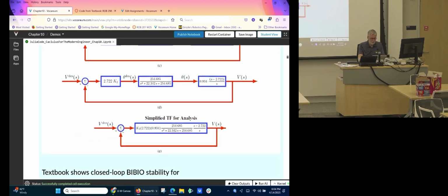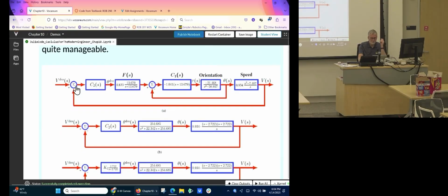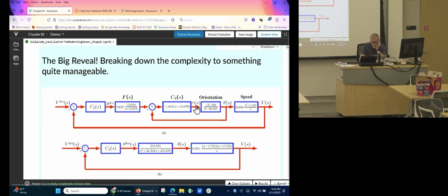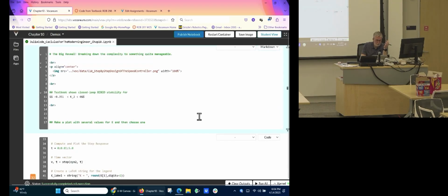Now what I want to do is the following. Here's the torque that's actually going into the Segway. This is a measurement, an IMU gives me this. And then I need to compute the velocity. I need to differentiate theta to get theta dot, and I need to differentiate phi, the wheel speed. So measuring from the encoder, I need to calculate its velocity multiplied by the angle. Okay, so this is an output, a measurement.